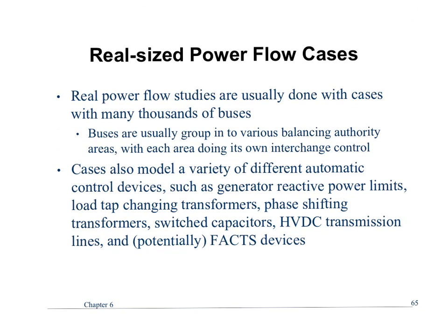Real size power flows, hundreds of thousands of buses are not uncommon. If you were to do a smaller industrial facility, 50 buses. So if you were going to buy a license for an analysis program, 50 buses would do fine for most places. If you're starting to get into the transmission and distribution level, 10,000 buses is not that uncommon. And so guess what? The companies that sell this analysis software, how do they mark it up? It's based on the number of allowable buses. So you can buy PowerTools for Windows for maybe $2-3 grand for 50 buses, but if you want to go to 2,000 buses or unlimited buses, you might have to pay $10,000-$12,000.